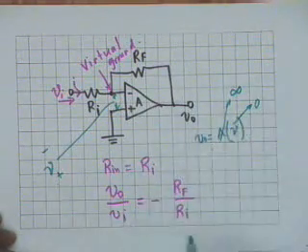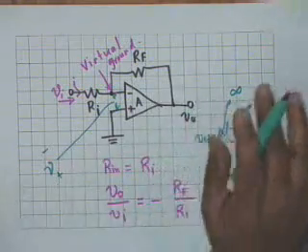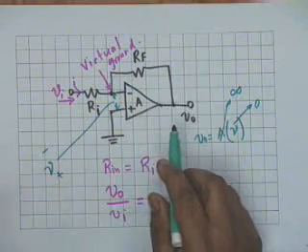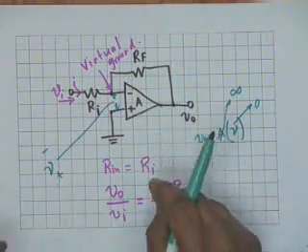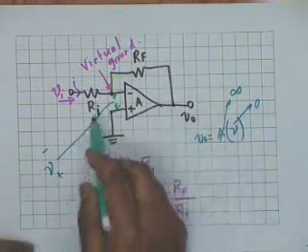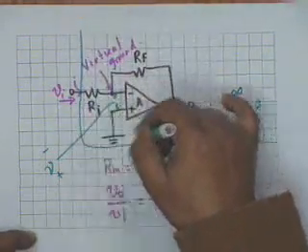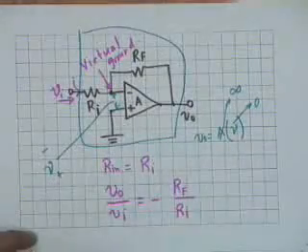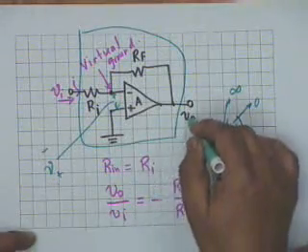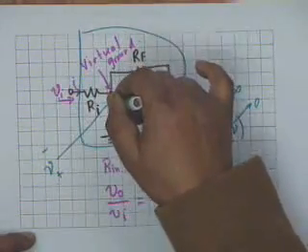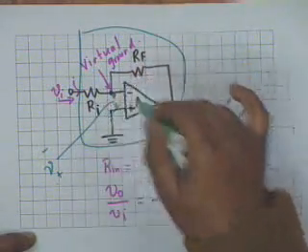This was the assumption. Now, the gain that we are now talking of is not what is applied at the inverting terminal or non-inverting terminal directly. It is applied through a resistance, and therefore the total amplifier circuit is this. It is V0 divided by this Vi, not what voltage appears here. Agreed?